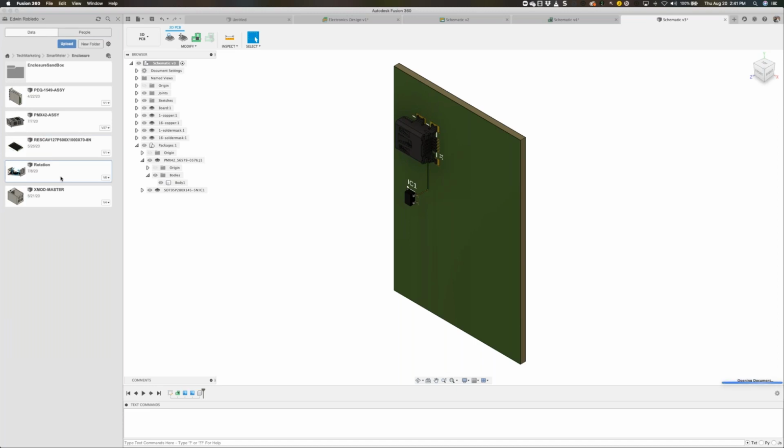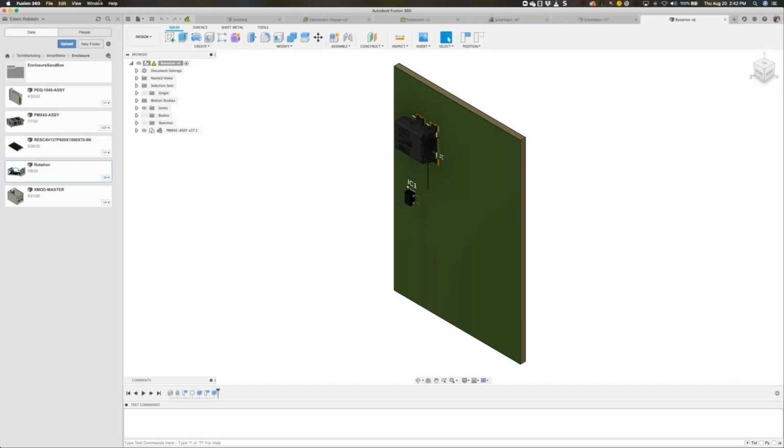I just want to do one more to see if I'm able to accomplish it really quick, Matthew. I keep on telling you about being able to capture the geometry of an enclosure to use it on my circuit board, and this is where I actually want to show it to you really quick, because this is the true electromechanical workflow. The whole idea behind this was to be able to capture complex geometries and use them on the PCB layout. That is the primary electromechanical workflow challenge that currently exists: the mechanical engineer being able to provide the complex geometry of an enclosure to the electronic engineer, an accurate one, so he knows where all the holes and standoffs are going to be.